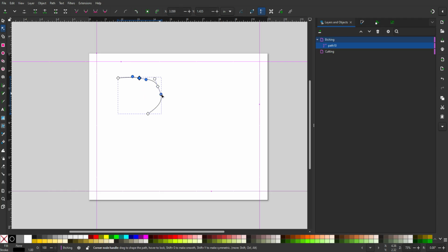So if I've got these two nodes selected, and I choose this break path, or delete segment, that's really what I wanted to do, between those nodes. Now they're gone. If I break them, I guess it made this extra line here that I can't edit. And if you double click on a line where you want a new node, it'll make a new node. Cool. So you'll play around with that when you're wanting to learn how to make shapes.